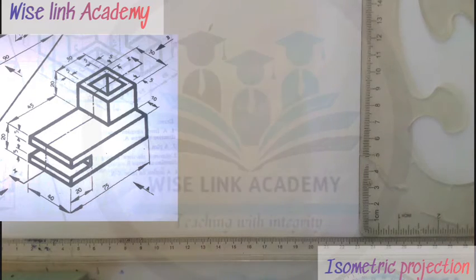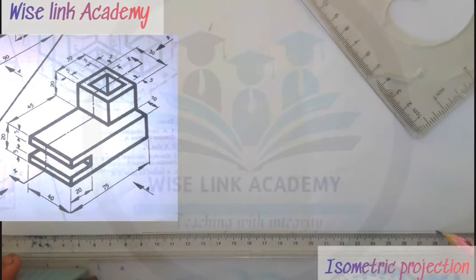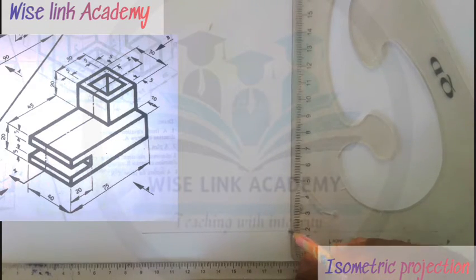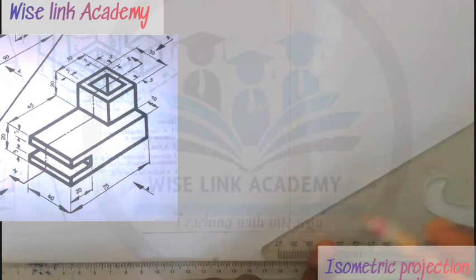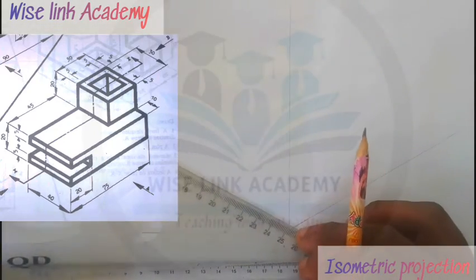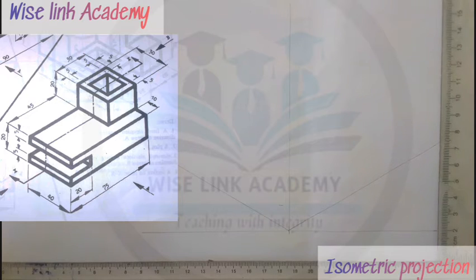So drawing my isometric axis, I'll have something of this nature. First, I will draw a horizontal line, a fixed horizontal line. Next up, I will draw a vertical line this way, right? Such that I will take this incline at 30 degrees this way, and next up an incline at 30 degrees, this part here too. So this is what we refer to as the isometric axis.